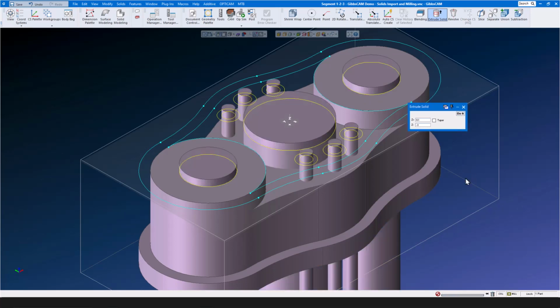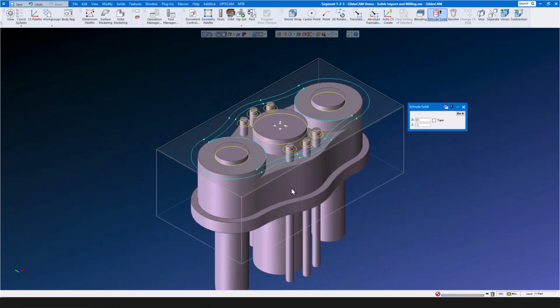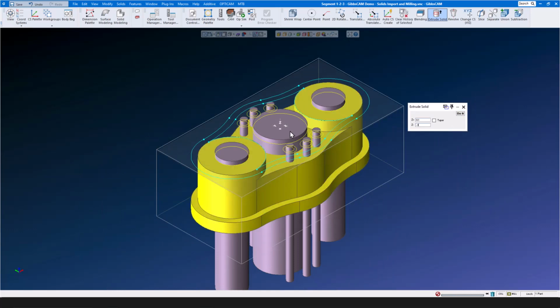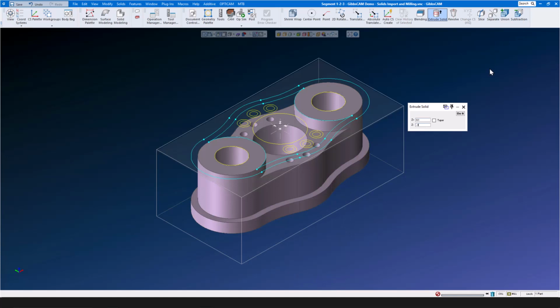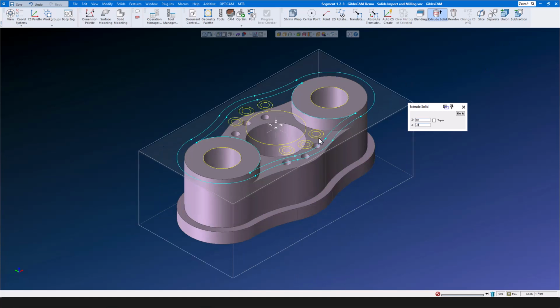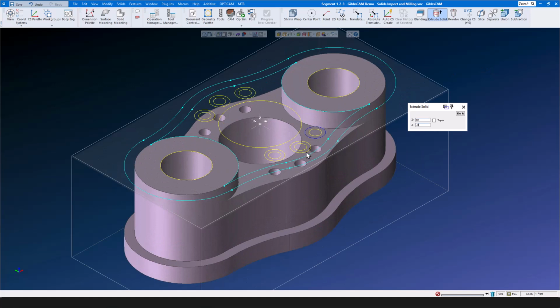We're going to extrude all of these circles at one time and then subtract them all at one time using the GibbsCAM subtraction. Now we have the counter bores, and the counter bores, we will extrude those as well, upwards of 0 and downwards of minus 0.250, minus 0.160. Yes, every data field in GibbsCAM is a calculator.